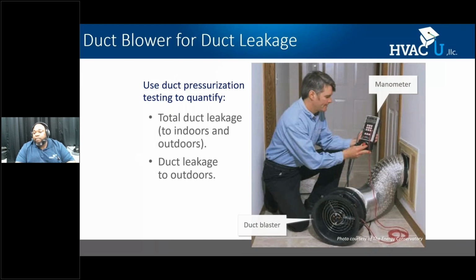And then I can perform a test where I compare the duct leakage. Is it inside the conditioned space or outside? And remember, if I have duct leakage to outside, it's a double whammy. I'm not getting the CFM to the proper place, and I have paid to condition that air, and it's being wasted and can never be recovered.